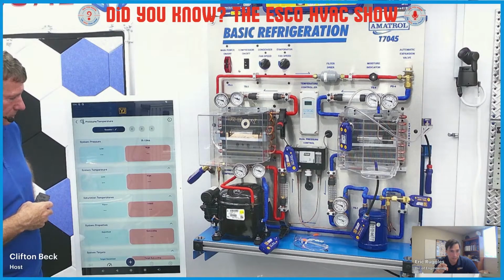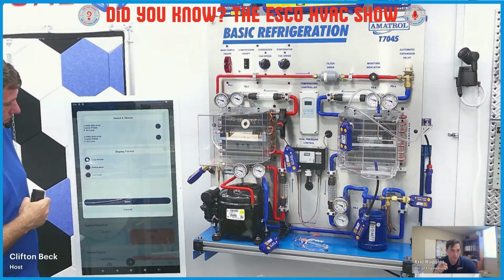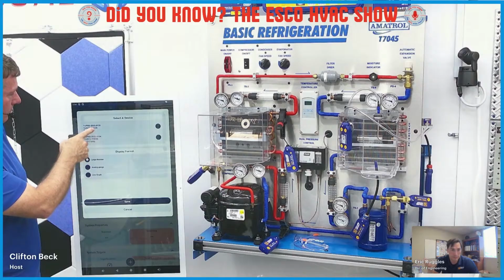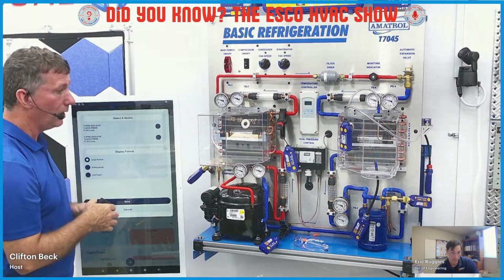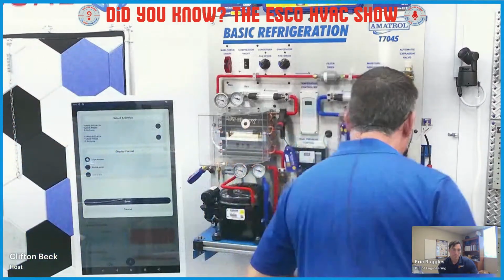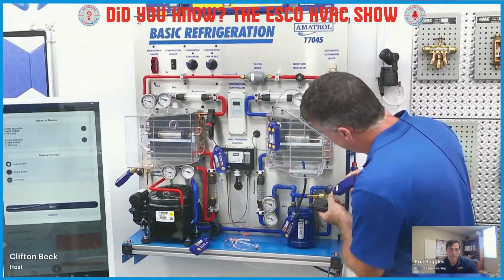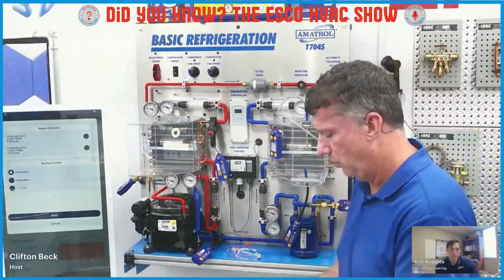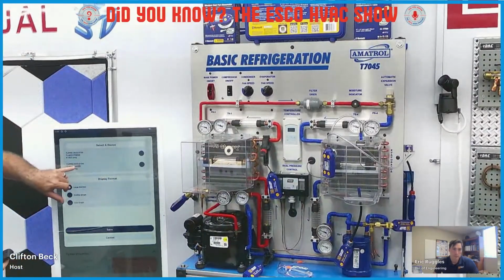So you're going to click on the low side, one of the blue bubbles, and then you're going to pick which sensor. Click the radio button of the top two, one that's low. You can look on the back of the sensor to find the serial number. If the system's running, I may do that. Yep. Let me walk over here. I'll look on the back. I'm just going to swivel this one around. 9104. Yeah, there it is. So 9104 is our actual low side. So I would pick that one.